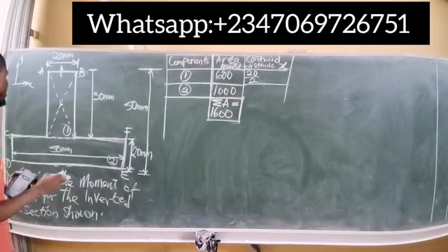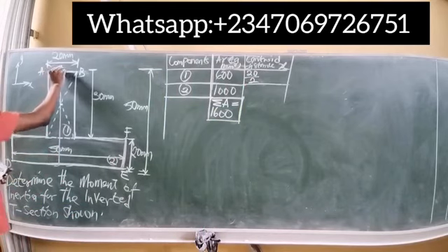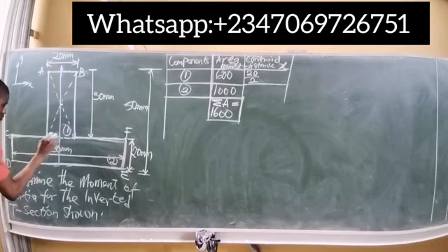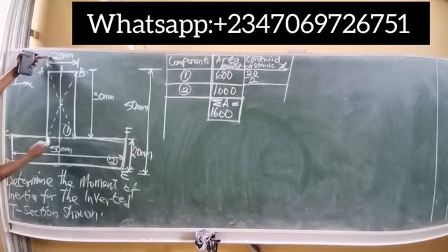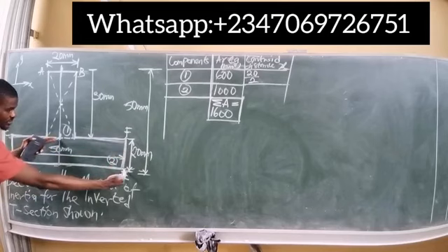But it doesn't end there. After cutting this shape into two, you need to take it down to the reference line. So cutting here into 2 is the same as cutting this point into 2. That's simply bisecting 20, because this is also the width for that first segment. So if I bisect 20 into 2, I will simply have 20 divided by 2, which is simply 10 and 10. But then that is cutting this point into 2, and I have to take it down to the reference line. Like I said, you always take all of them down to the reference line. So moving from this point to the reference line, I have covered this height of 20 millimeters.